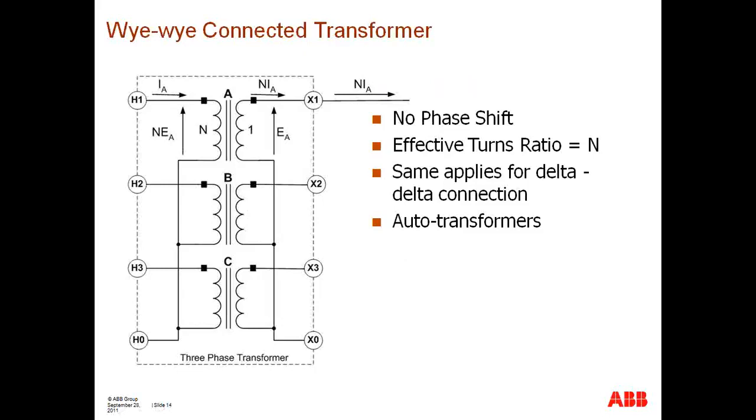the transformer. So we have here the first case where we have a Y connection. And a Y connection can be identified. Number one, there's not going to be any phase shift between the voltage between H1 and H0 versus the voltage between X1 and X0.